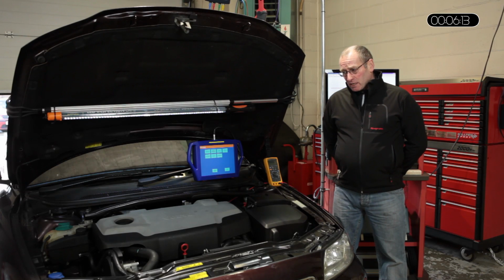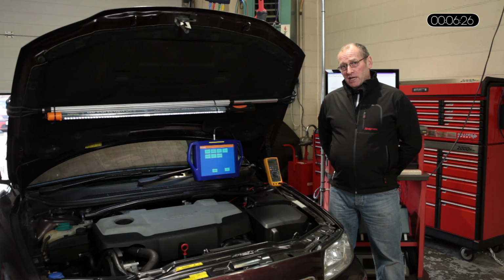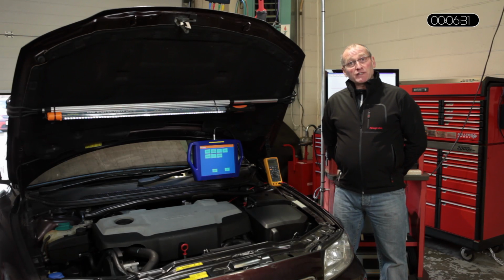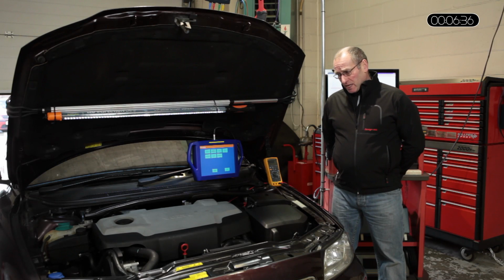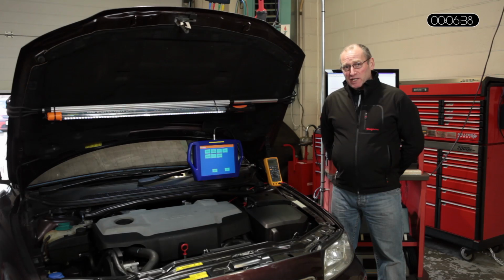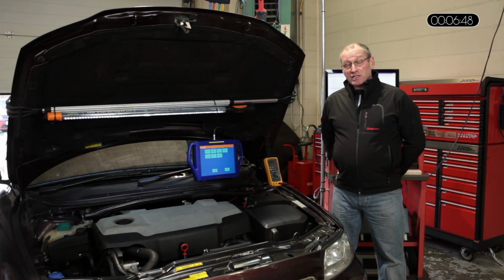We then, having soaked it overnight, steam cleaned the DPF in a reverse direction. Now, I'm happy to accept an argument that you should not steam them out, that steaming out may affect the substrate to such an extent that it effectively doesn't treat the carbon particles in the correct way. We had some financial restraints on this repair, and we chose that as the most sensible route. We're also interested to see if the cleaning process was effective. It turns out that it was effective.